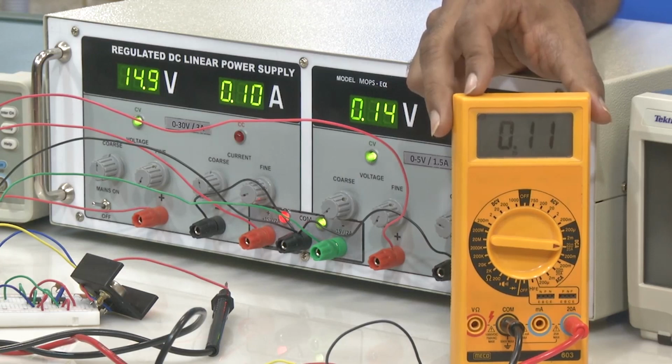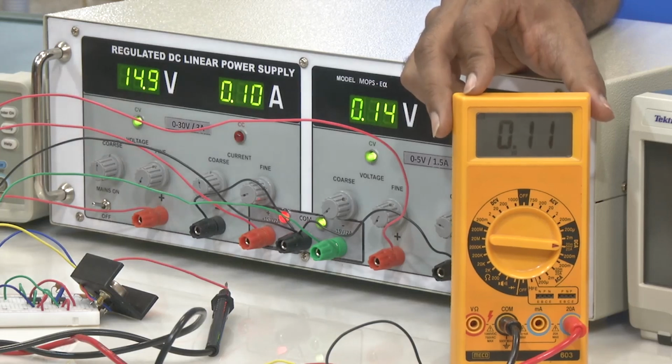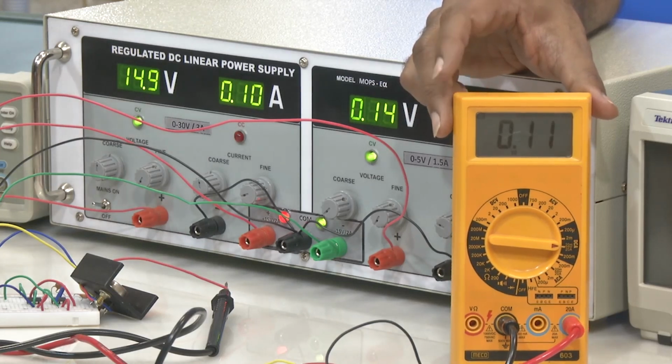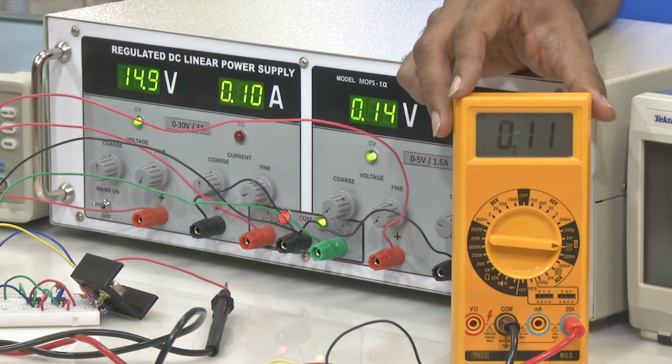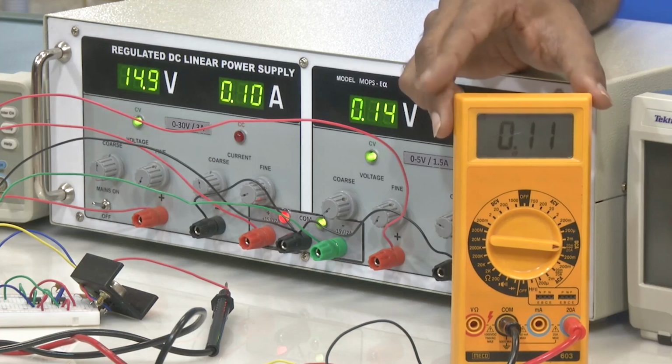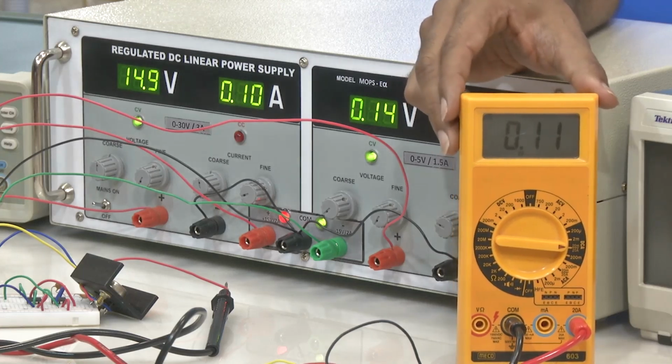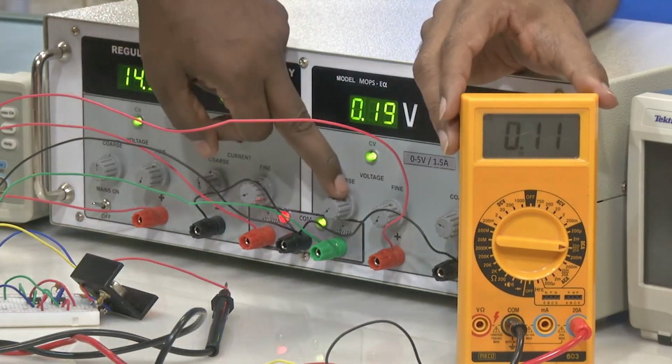There is some loss, and that is obvious because of the circuit. There are components, we will have a lot of voltage drop across the components, and you can see basically the loss is due to the transistor that is connected in the circuit. But anyway, the point is that now we have designed a voltage to current converter with a simple circuit that you are looking at here.